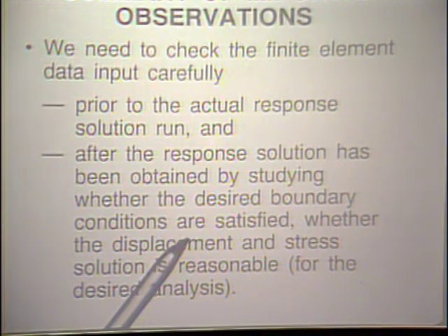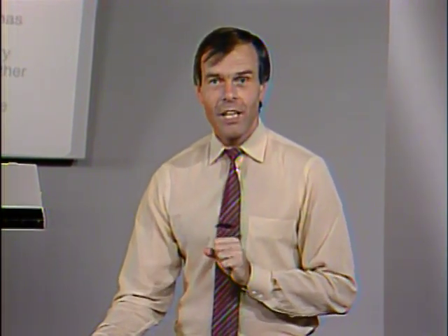Remember, in our analysis, we did this as well, and we found by looking at the boundary conditions, the way they were represented in the actual solution, that we had actually made an error. In other words, we looked at the deformed mesh, and the boundary conditions on the deformed mesh in our first analysis showed that we had fixed the boundary at the bottom of the mesh, which was an error. So it is very important to go through this step to look very closely whether the boundary conditions are actually satisfied on the mesh that you have been using in the right way.